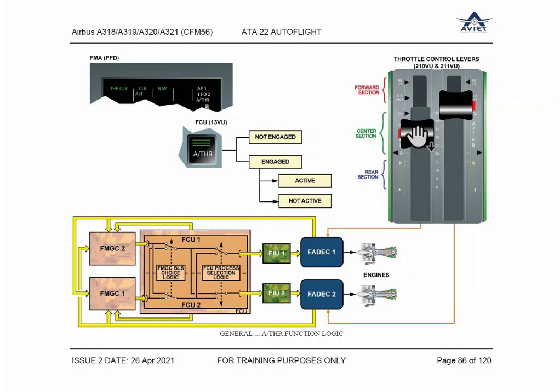Correct? So as far as auto thrust is concerned, climb is the maximum limit for double engine operation. If you are in single engine operation and want to get auto thrust, then you have to keep the lever at maximum, up to the flex. You will get the full range of auto thrust up to the flex. Is that clear? Yes, sir.